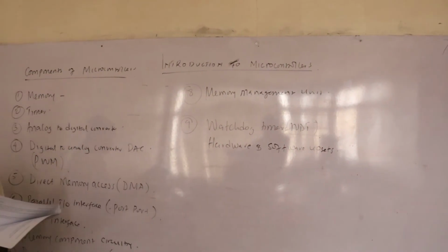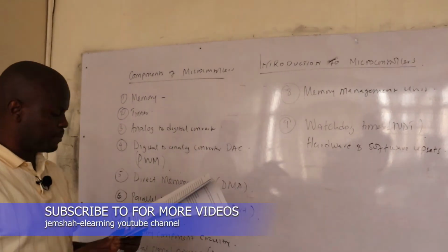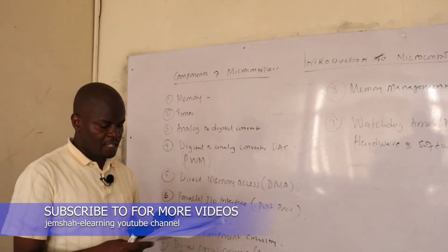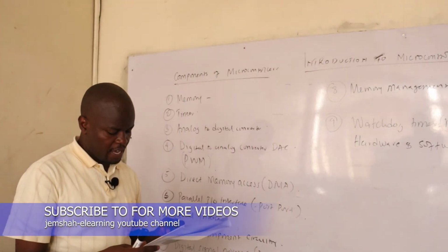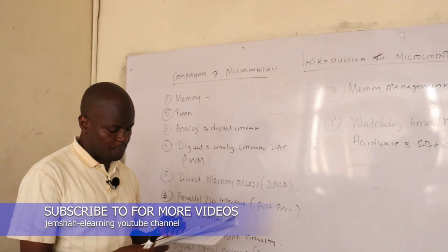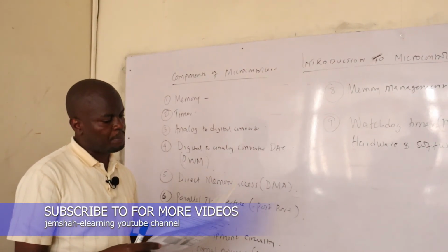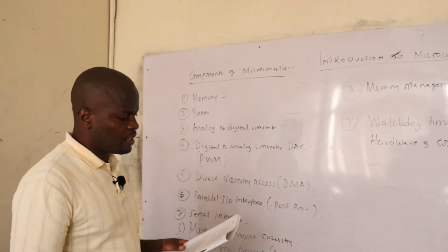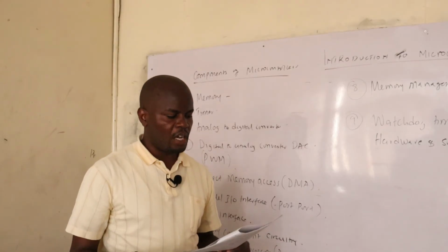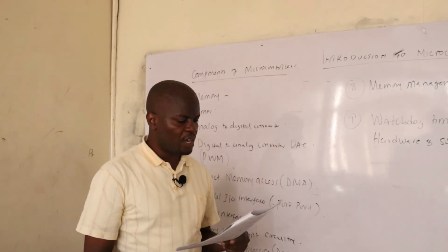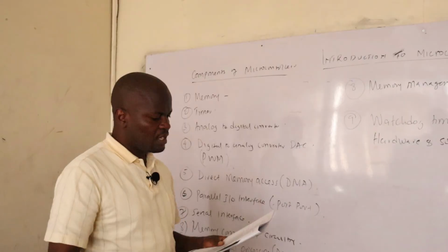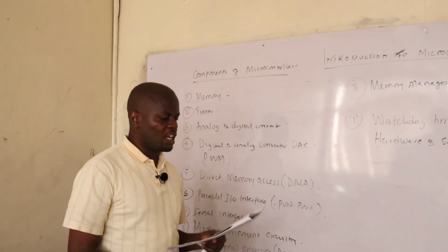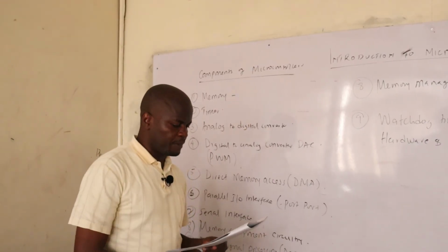Basically, there is always a time that it takes for a given process to be completed. If it takes more time than that, then the Watchdog Timer will tell the system that there is a problem. The problems can be a result of electrical noise or electrostatic discharge, or maybe due to any hardware-related problems. And if this happens, then there will be overflow, and a hardware reset is initiated in order to restart the microcontroller.